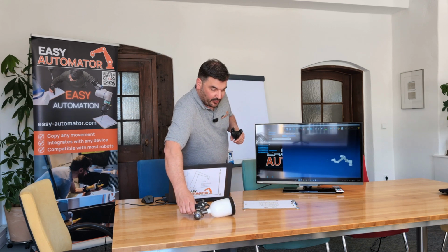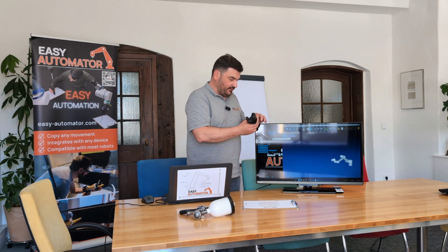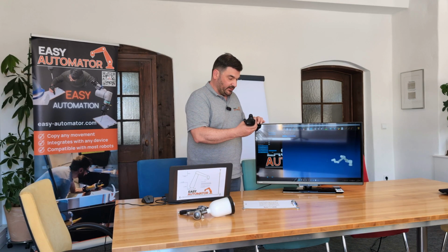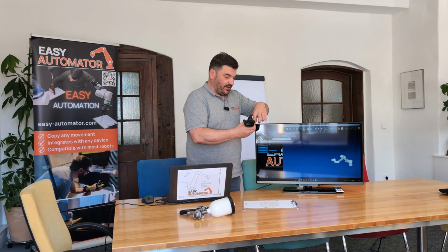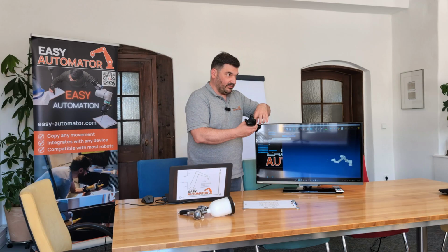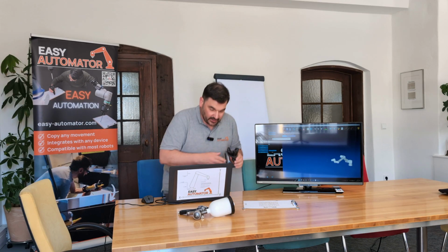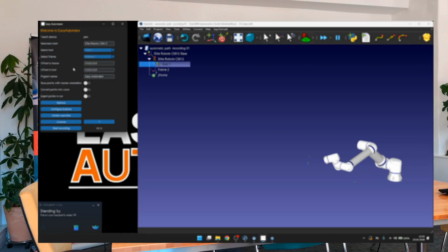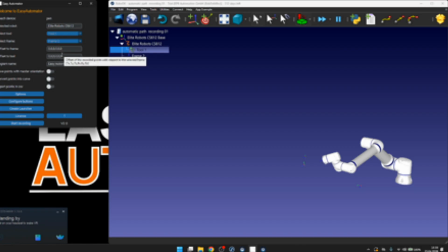Therefore, I will apply a tool offset. I will touch the point so that this point is exactly defined, but the tool should come only to this position. I will define it as 8 centimeters, or 80 millimeters, away from the surface. To do so, I go to the offset to tool, and the tool offset will be minus 80 millimeters. This would be the plus direction, and this is the negative direction.